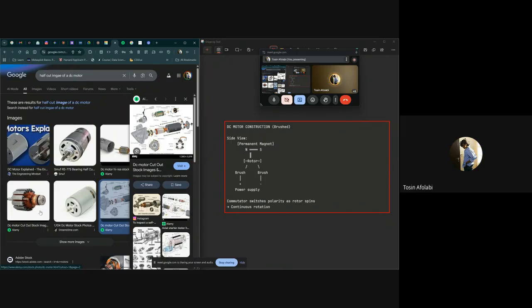While for a 50% duty cycle, the Arduino uses PWM to send about 2.5 volts. That's like cutting the volts in half, so that's half the speed. Then same thing with 25%. That's 1.25 volts, which is a quarter of the speed. It's also like that for 75%, and so on in general.